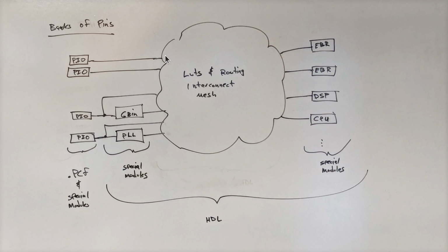Blinky is more sophisticated, and I've got that in the same repo as these examples. We'll talk more about Blinky in another video because it'll require a little more thought and discussion, because if we bring a signal in here and just send it back out, we're not really doing anything. We're simply connecting. If you want to blink something on and off, what we need is a circuit that periodically does something. And it goes on and off and on and off. And that means we're going to need to be aware of time, and we're going to have to figure out how to create a delay and all these other things. It's not hard once you know how, but it's not as easy as a simple combinational circuit,